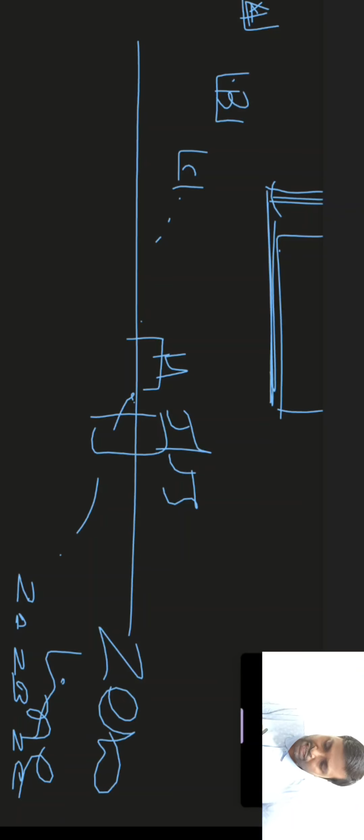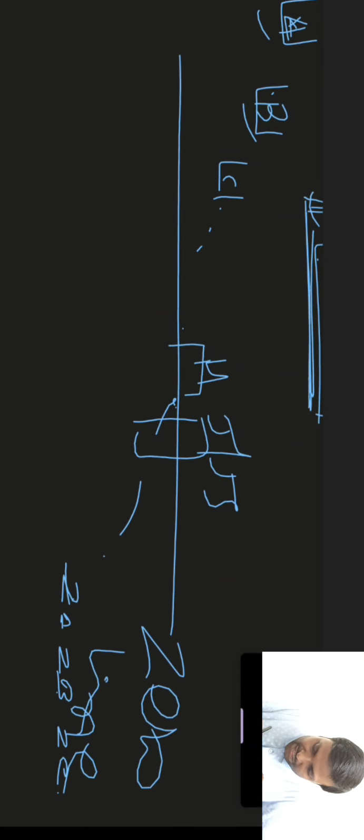Since we are writing alphabets or combinations of alphabets in capital letters, this capital letter in the standard code is used to represent the fundamental deviation for the hole. If you want to show the fundamental deviation for the shaft, the alphabets will be in lower case. So the fundamental deviation of the shaft is represented like this. This will be called a.